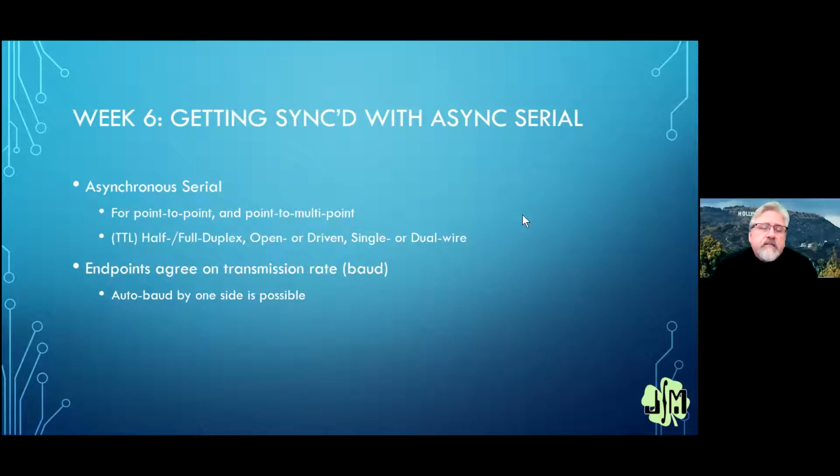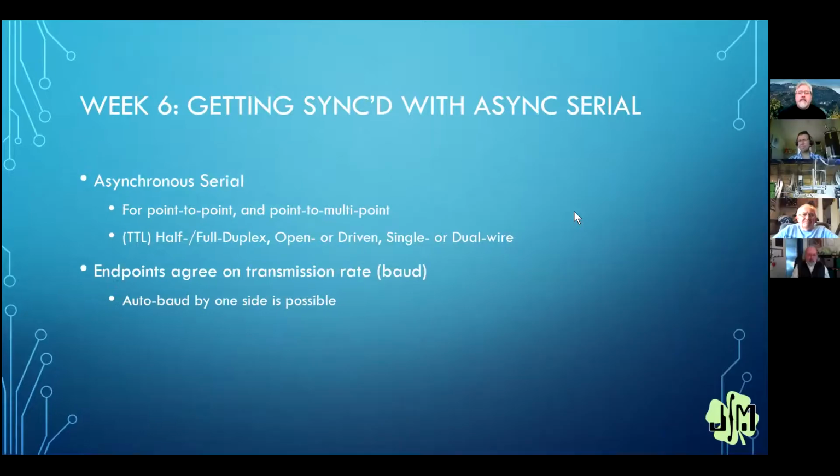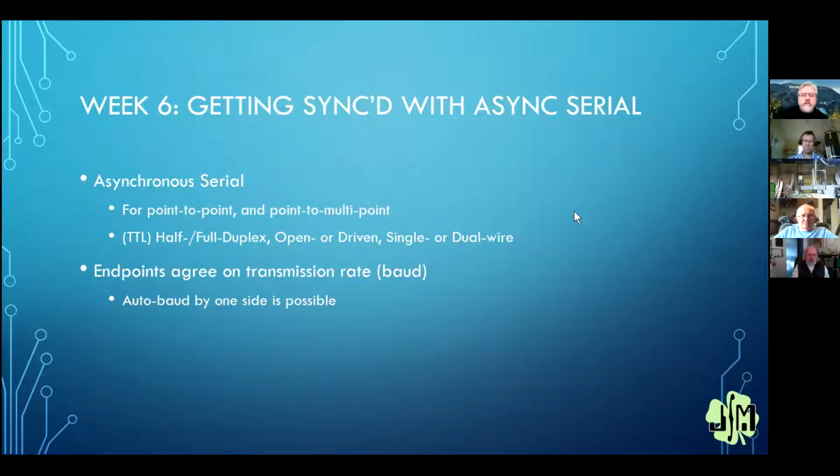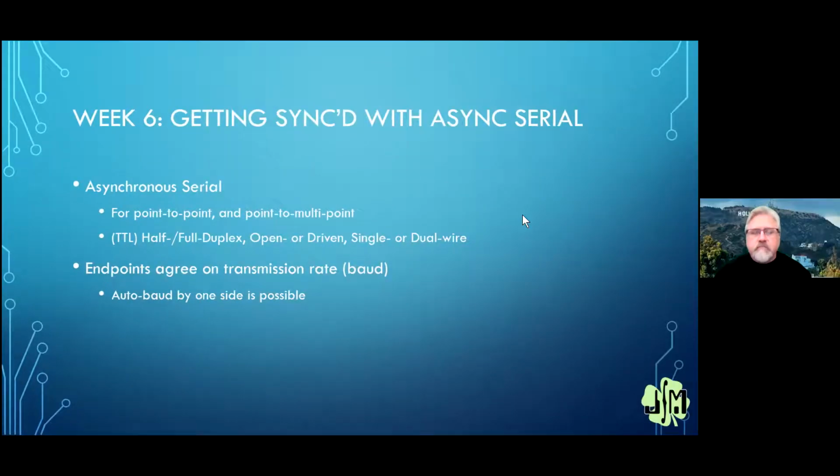In the early days of the Basic Stamps, serial LCDs kind of came into life. And that was the Basic Stamp sending messages through serial mode to an LCD to display on it. We did that in a previous tutorial, but we used, instead of straight asynchronous serial, I2C, another type of serial mechanism.